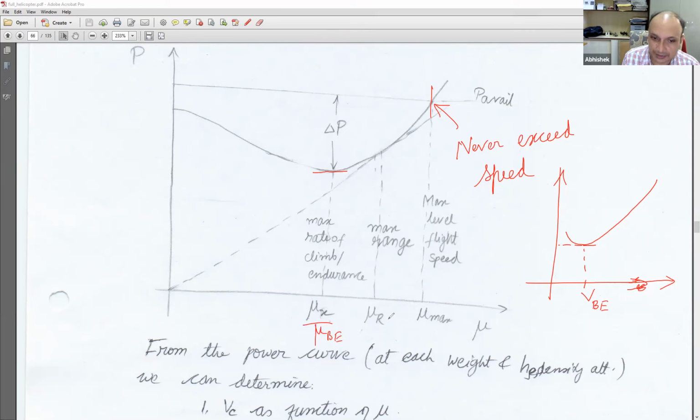And the range. Now the max range depends on what factor? What determines the maximum range? Drag. Not just drag alone. It is the same as for airplanes also. L by D ratio. Exactly, L by D ratio, yes. So what is L by D ratio known as? There is another name for that. Aerodynamic efficiency. Propulsive efficiency, yes. So it's propulsive efficiency which actually determines your maximum range.